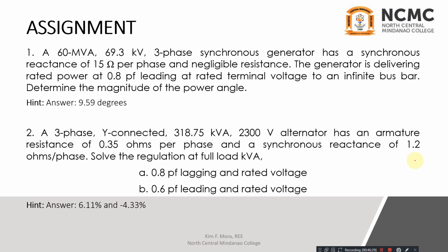So for number 1, a 60 MVA 69.3 kilovolts three-phase synchronous generator has a synchronous reactance of 15 ohms per phase and negligible resistance, so R is equal to 0. Then the generator is delivering rated power at 0.8 PF leading at rated terminal voltage to an infinite bus bar.